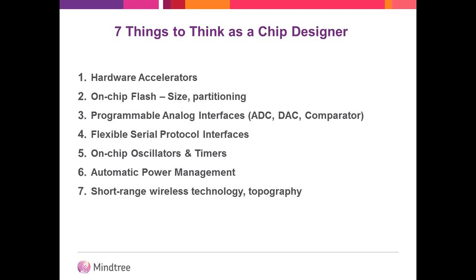The fourth aspect is flexible serial protocol interfaces. Today's chips already have a lot of UARTs and SPIs and a lot of different serial interface protocols. But what you probably need to look at is their flexibility: do they support multiple different combinations of uses, and even having a common platform-like interface, but then making it programmable based on whether you want to use it as a UART or an SPI or a different kind of serial interface.